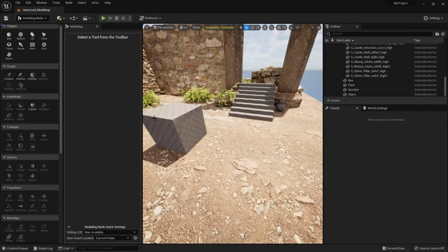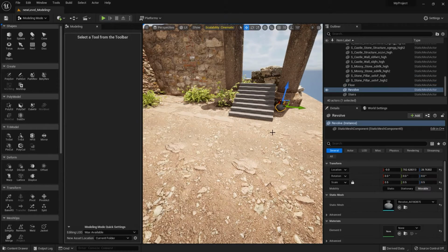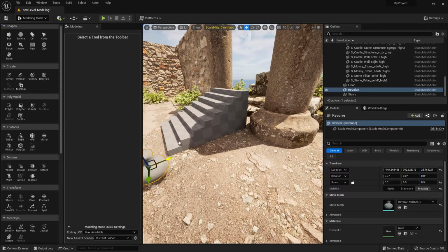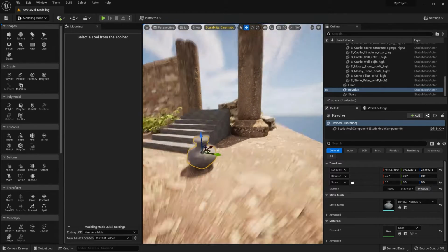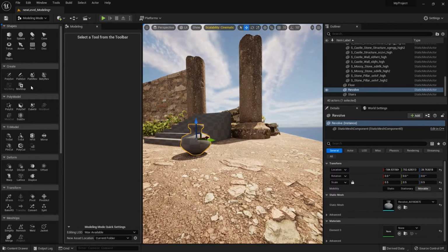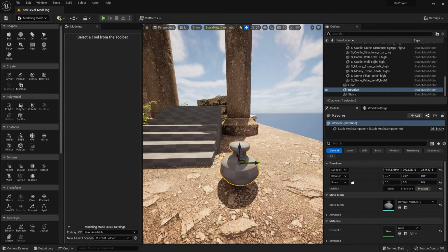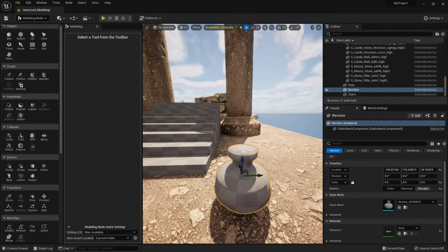With that said, let's talk about how we can actually create our own polygroups and not rely on primitives. Because, for example, something like this, we just made very quickly out of path revolve, so there were no options to know where or what mode to choose for polygroup. So what am I going to do in this one? Well, the good news is you can actually paint on triangles and turn them into polygroups.